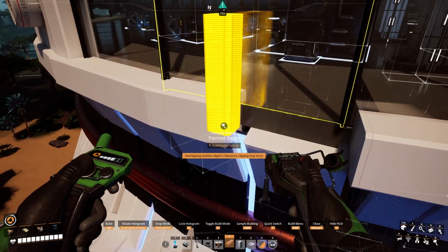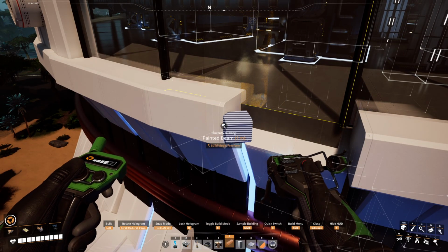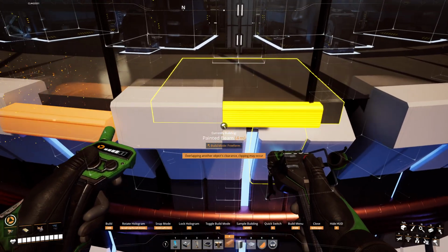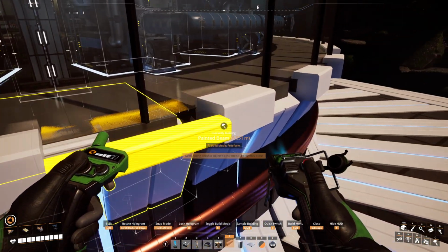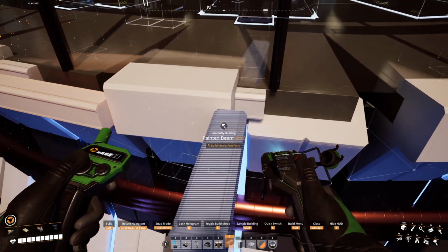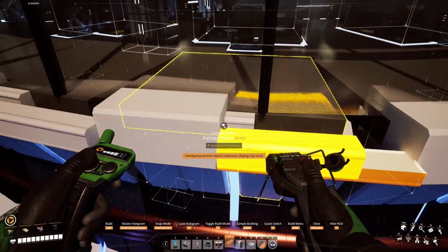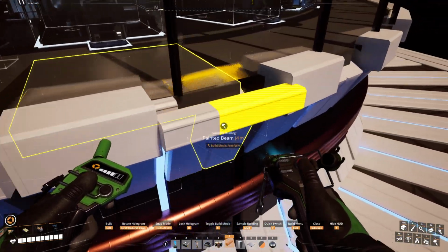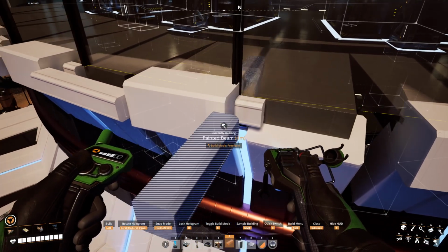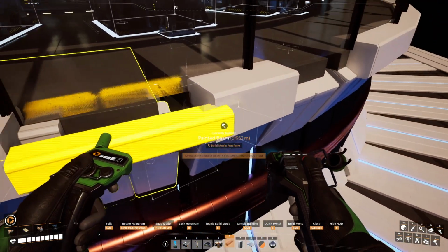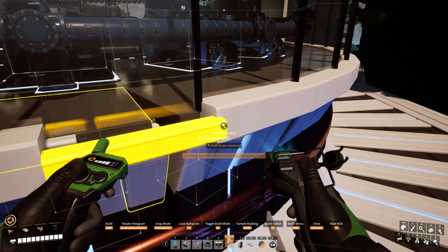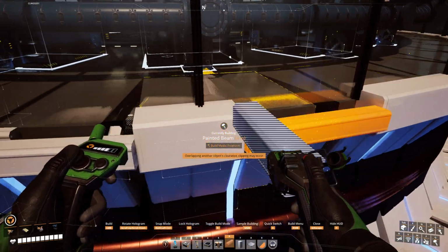So beam again. In free mode, you want to lock it on that edge, and then over there. So same story over here. Lock it in, and again. The big thing with this technique is you want this beam to be more than 4 meters. Then this will work perfectly fine. So you'll see there, 5 point something. This obviously is going to be a bit longer. It doesn't matter how long it is as long as it's more than 4.